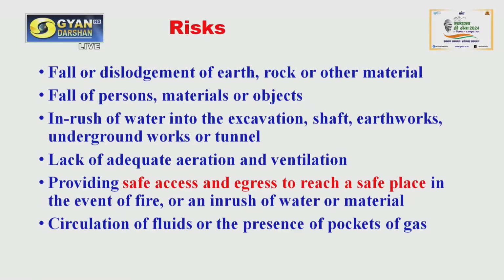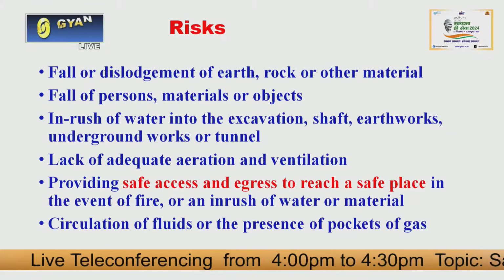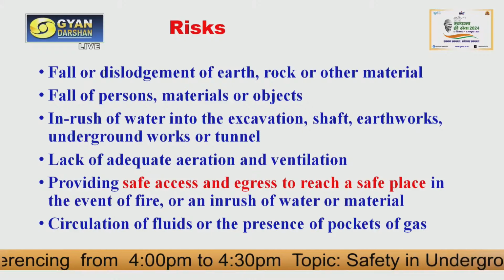Then there is lack of adequate aeration and ventilation, because when we are working underground, the flow of air is obstructed. So we artificially provide air so that the workers can get oxygen, and there is a problem of getting a proper amount of oxygen and of ventilation. Then there is a problem of safe access and egress to reach a safe place in case of fire or inrush of water or other materials.